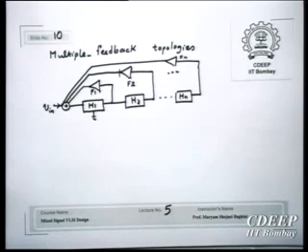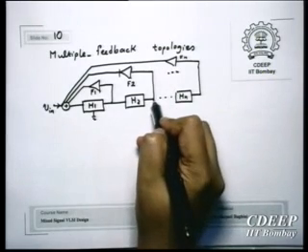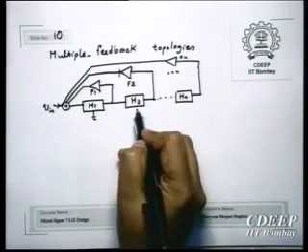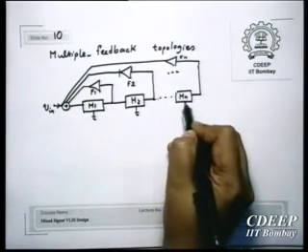So it's a combination of both. Now we can decide what the order of each filter should be and how we can control each one of them separately. It's very common to choose order 2. Therefore, most of these H stages are biquads.